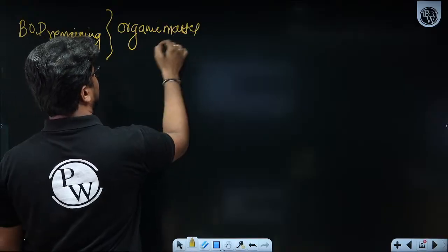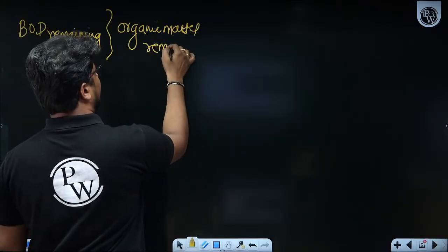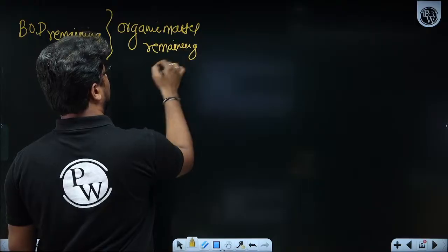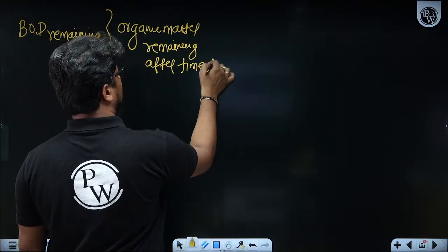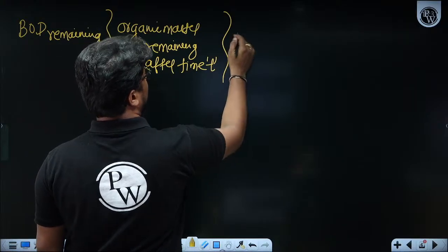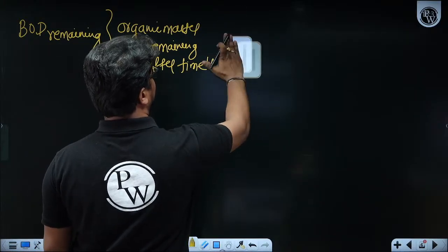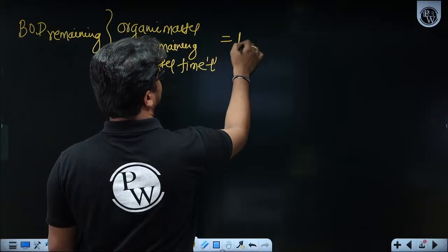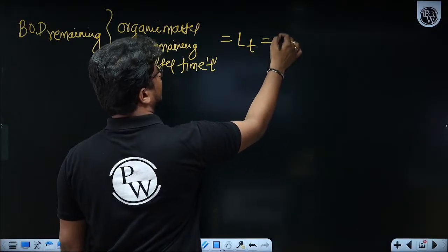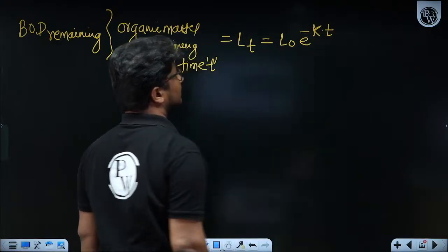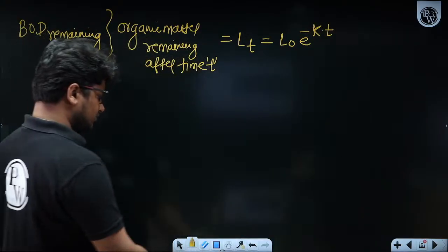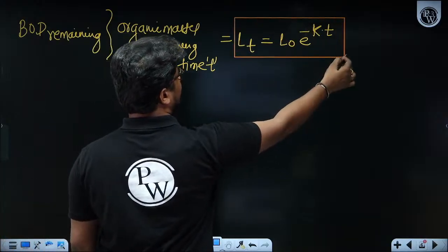Organic matter remaining after time t, and that is equal to something we write as Lt, and that is equal to L0 e to the power minus k into t. This became a formula for you.